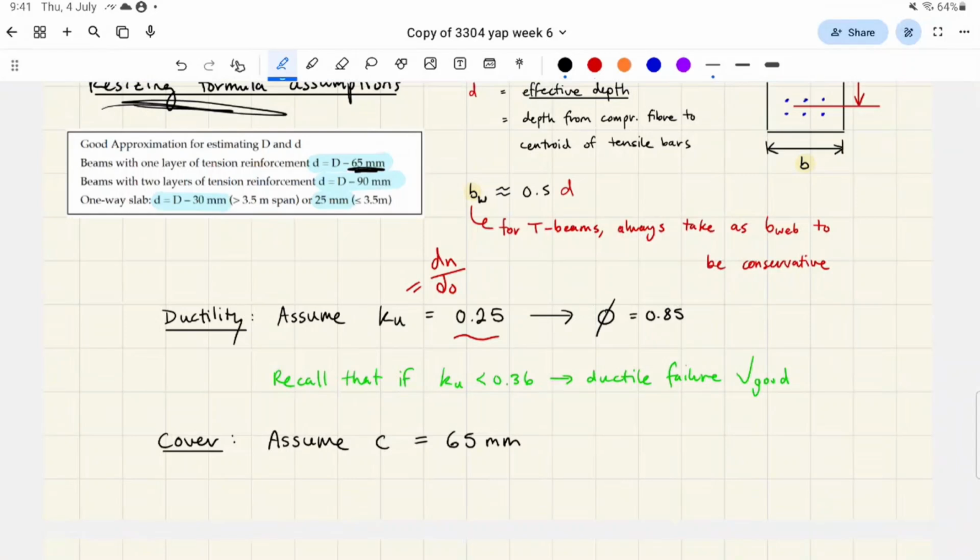Once it starts to crack, it's essentially as good as gone. But if you have steel there as well, the cracking is a visual sign of the steel yielding. Either it goes from uncracked to completely failed straight away if it's unreinforced, or the cracking is a good sign that the steel is doing its job properly.